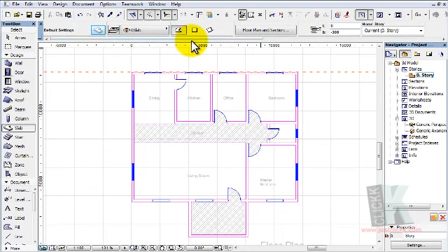We'll take care of coloration during the rendering of the project. Now for this elevation aspect, the best practice for me, I think, is to let your base be 0, while the top elevation of the slab should be at the desired height of the slab.